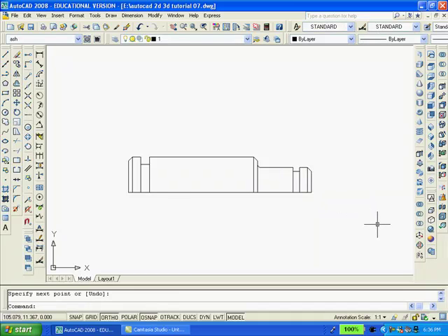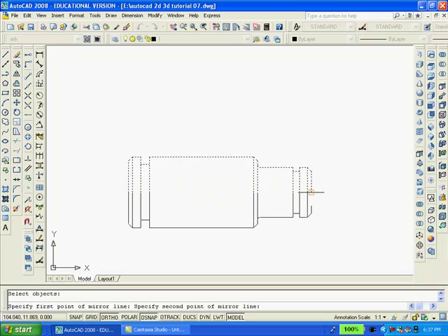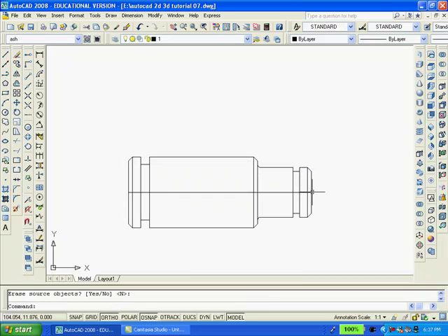In my next step, I'm going to use the mirror command with a crossing window and mirror from one end of the baseline to the other without deleting it. In addition, I lengthened the center line. It does not show as a center line, so now I'm going to put it on a layer which I have center lines.